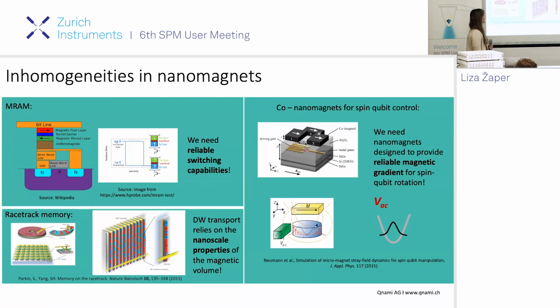So here on this image on the right, we can see a silicon germanium heterostructure. On their interface, there will be a 2DEG formed, and by applying a voltage on the driving gates, we can deplete the 2DEG and create 2 quantum dots. These 2 quantum dots essentially represent a spin qubit.